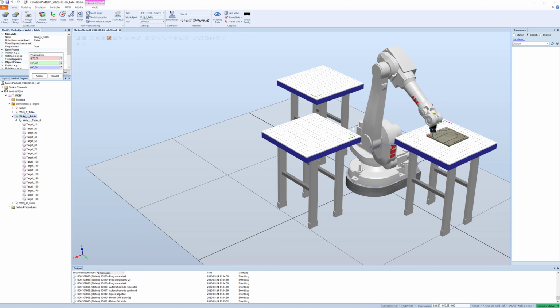And for this exercise we don't change anything. But for a later exercise, we do change the object frame. So this is actually the position and orientation of this frame here. Then we can have an added object frame somewhere on the table, at any place, and that will be called the object frame here, where we can put new values in relation to the user frame defined here.